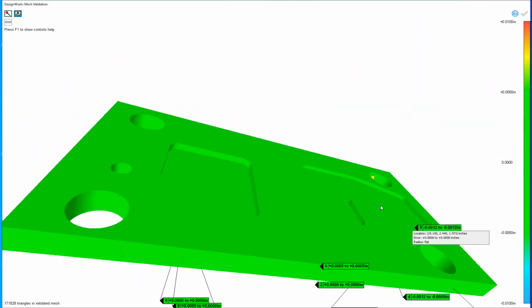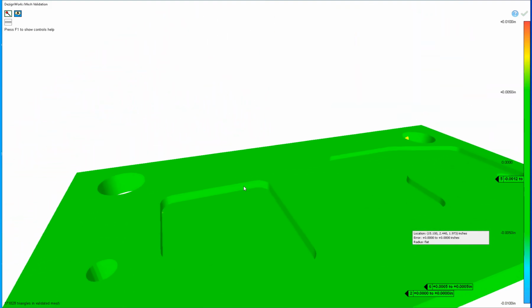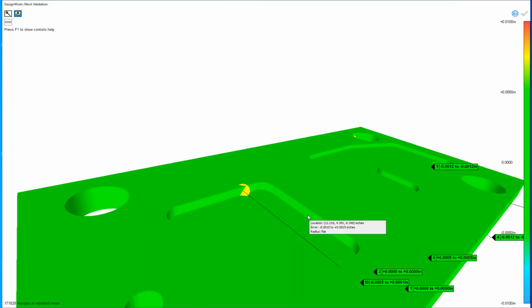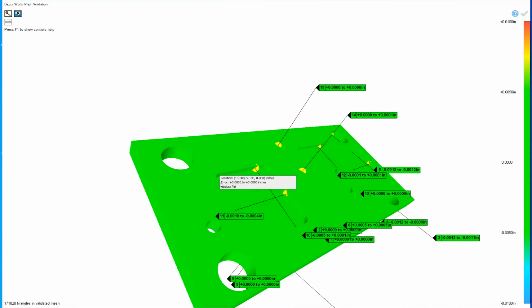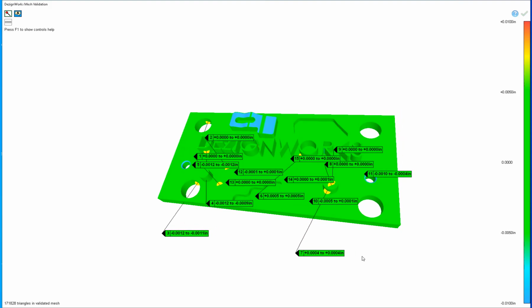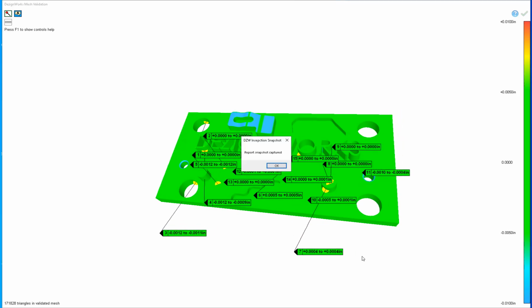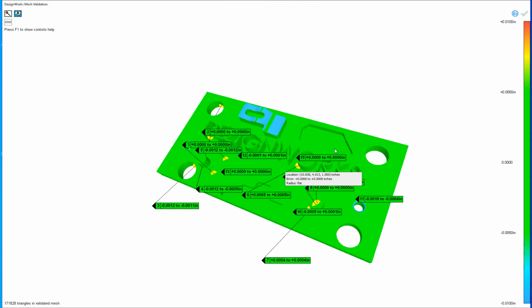Notice the big enhancement is you can have features on any side you want. And it picked these differently, even though they have the same depth. When you go ahead and use the inspection tool, you can write this out, up to 8 views. You can also edit these and drag them.